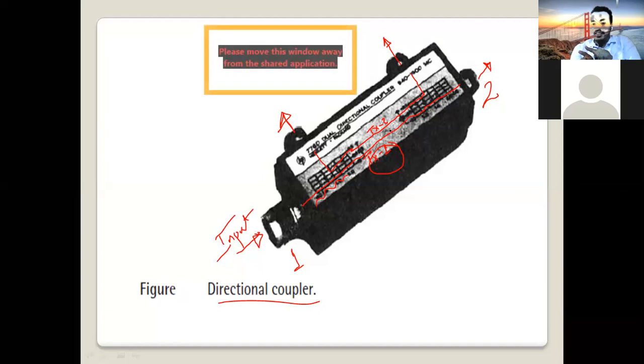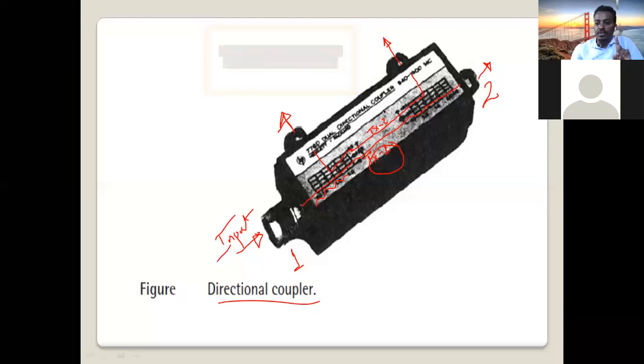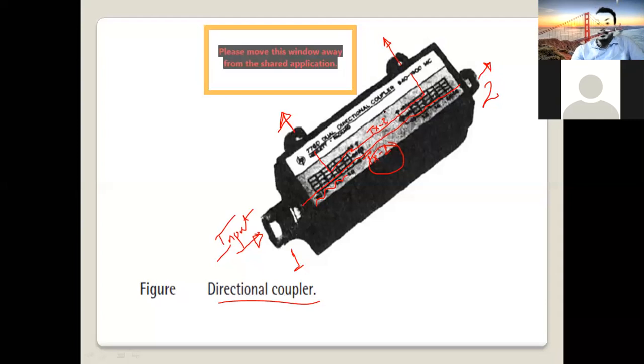There is no physical contact, but still the signal is coupled, just like a transformer. In a transformer there are 2 windings with no contact between them; between them we have either air or some core material. When you apply primary current on the first winding, you get current on the secondary winding by magnetic coupling. Similarly here, by the coupling process, a small part of the signal from transmission line 1 will be coupled or transferred to transmission line 2.